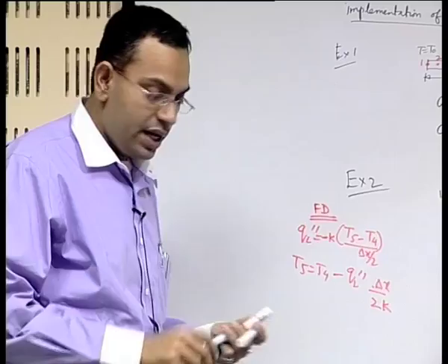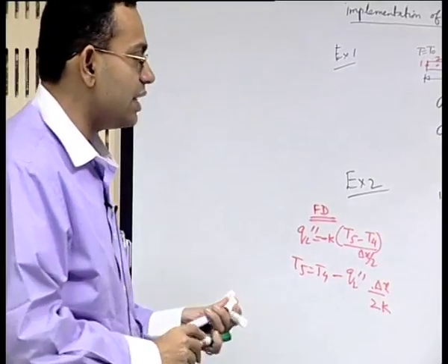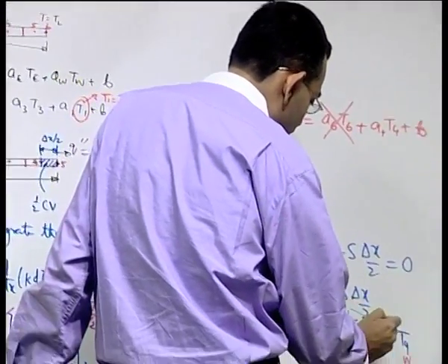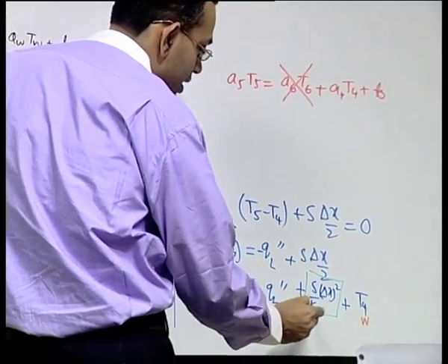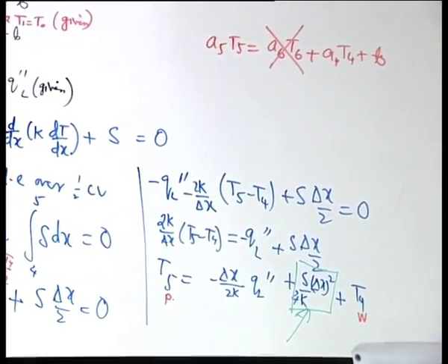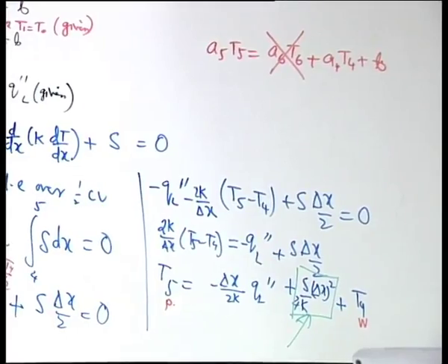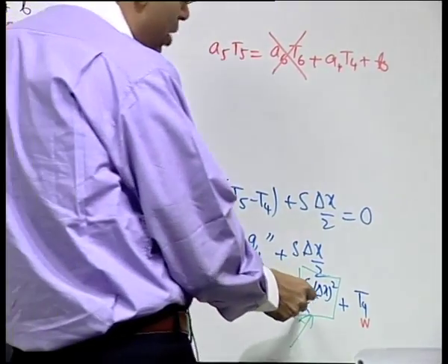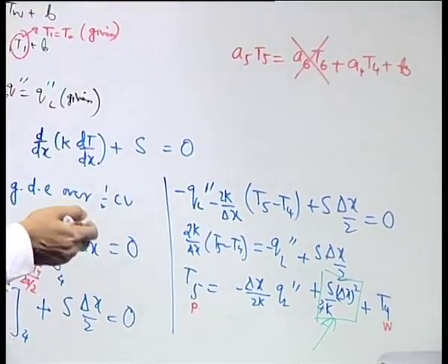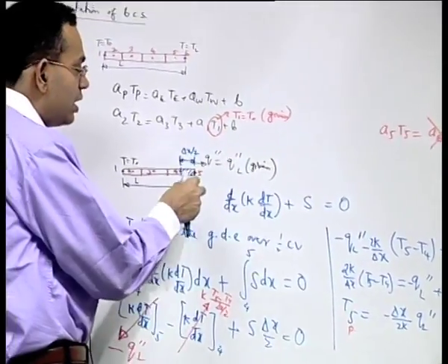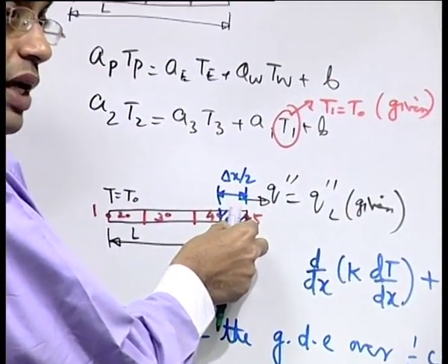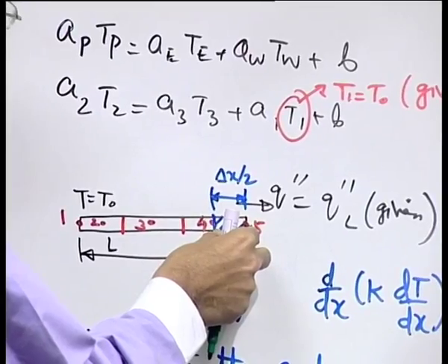So with this one line exercise, you can see that the difference between this finite difference and the finite volume way of writing the boundary term is the existence of the source term. It seems to be more logical to have the source term in the implementation of the boundary condition here in the finite volume method, because what it tries to do, it tries to represent the boundary condition through the conservation of energy over the small control volume, and there the heat source definitely plays a role.